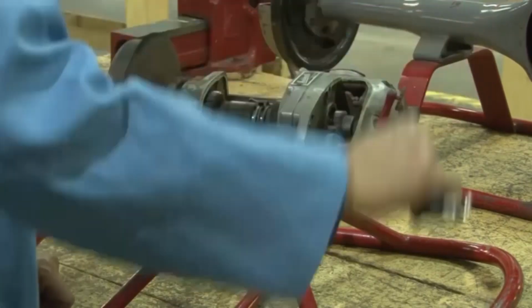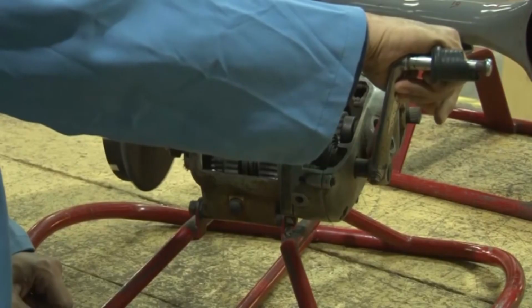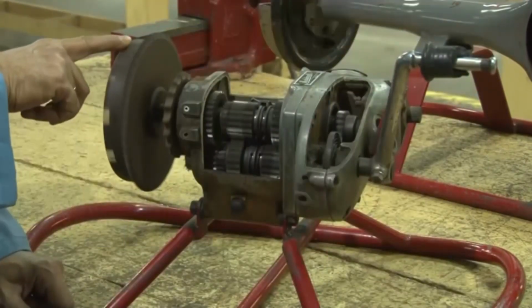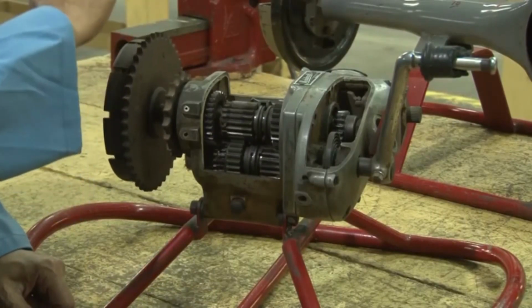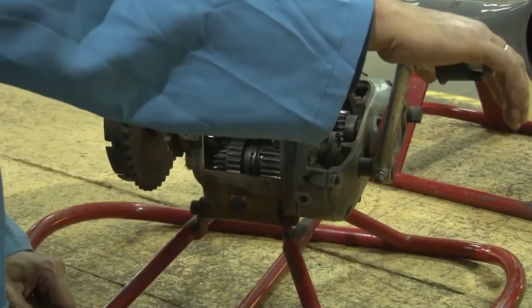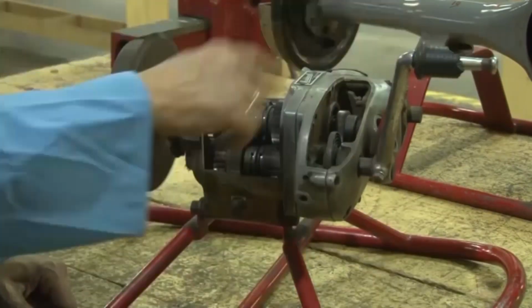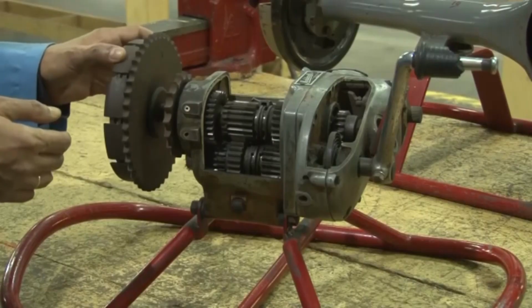So, here this is the kick start. You can see the ratchet mechanism which makes that sound, all right, and when you are kicking you can see that this is moving. So, this rotation is being imitated by this kicking mechanism, all right, and after that with inertia it can actually get started, as it is done in the case of a motorcycle and scooter.